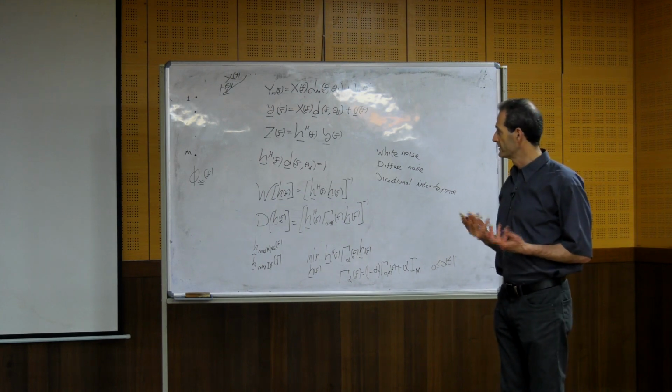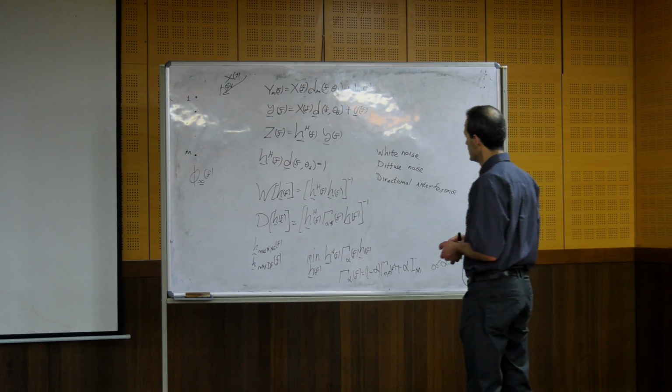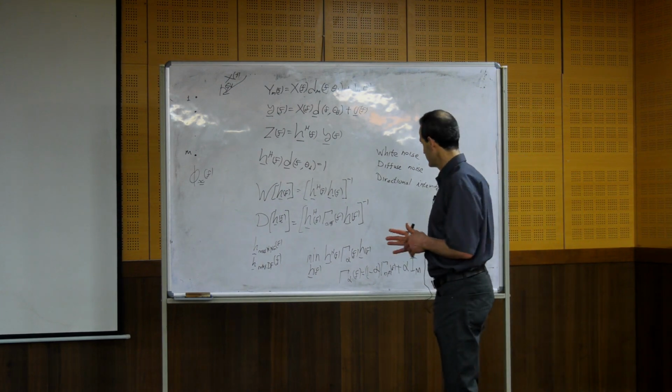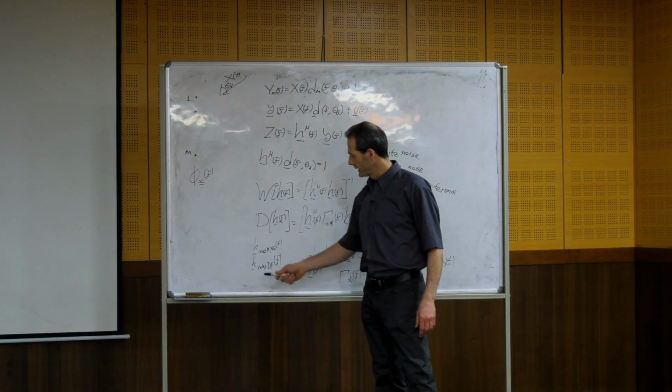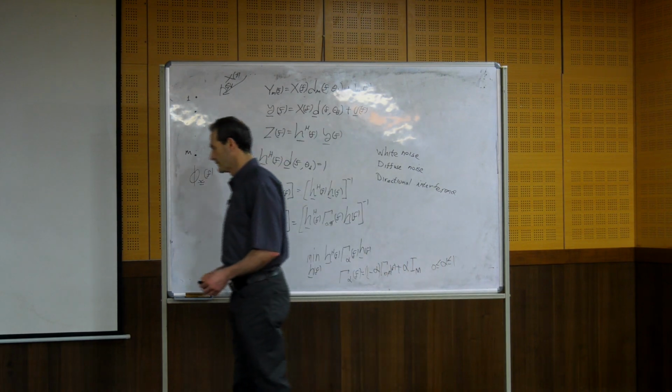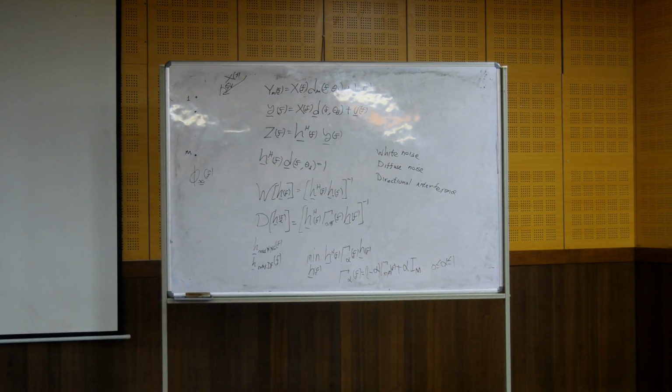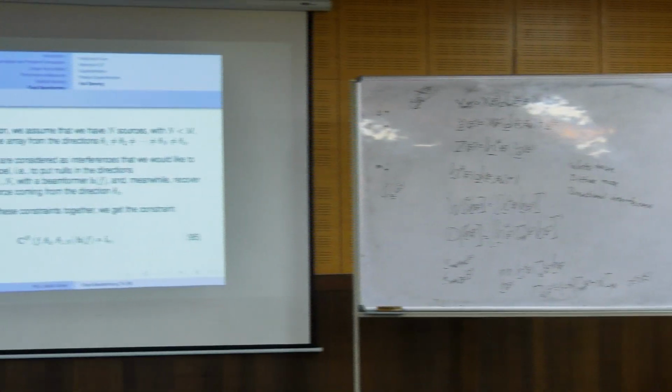So how do we add such information? We call it null steering. Okay? So here we talked about max white noise gain, max DF, and we have some trade-off between them. And now we talk about additional information. Okay, so the more information that you have, you can use it. For null steering, we assume that we have some interferences that come from certain directions. Let's call these directions theta n, 1, 2, and so on, depending.